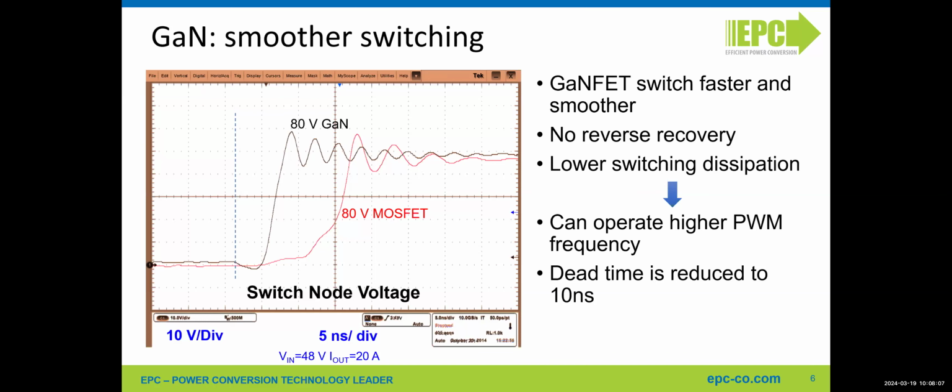Then, depending on the board, depending on the amount of current you want to switch, it may be 20 nanoseconds, or 50 nanoseconds, or 75 nanoseconds. For those boards where some of our customers are doing 300 amps, they're using 100 nanoseconds. That is really different from the typical values that are used with MOSFETs.